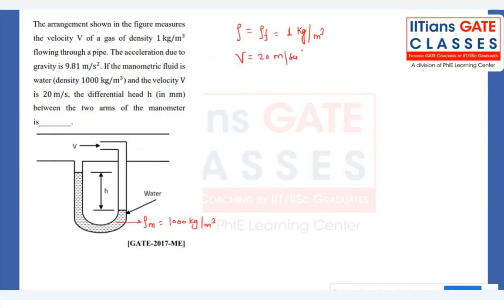They are asking for the differential head between the two arms of the manometer. For our case, this is x. So we know the formula directly. What is the formula we have? V equals square root of 2g x (rho m by rho minus 1). So this is 20.